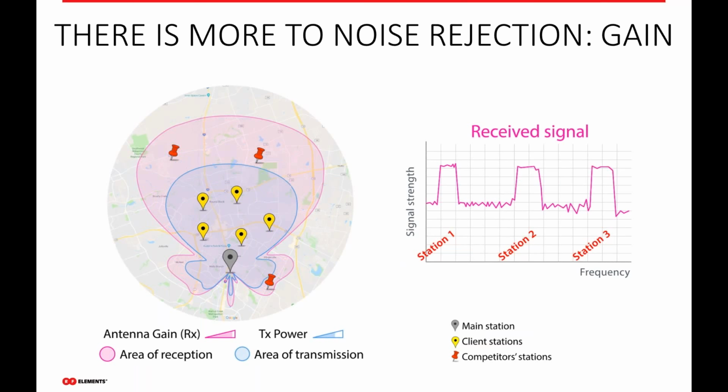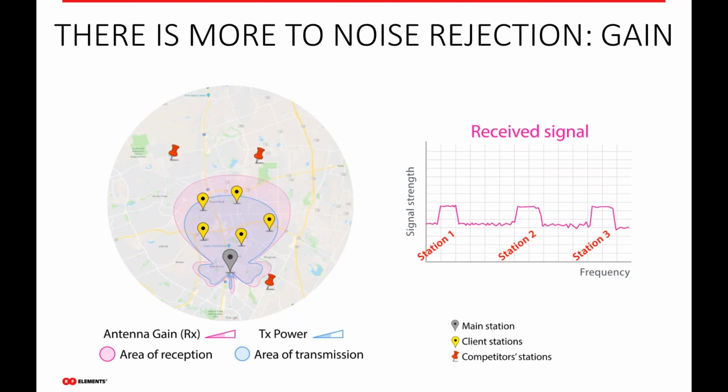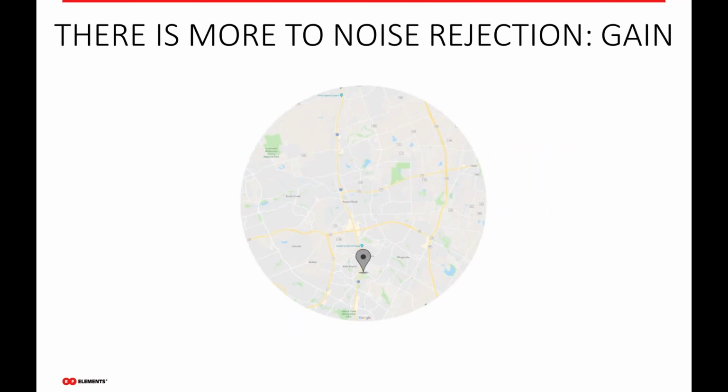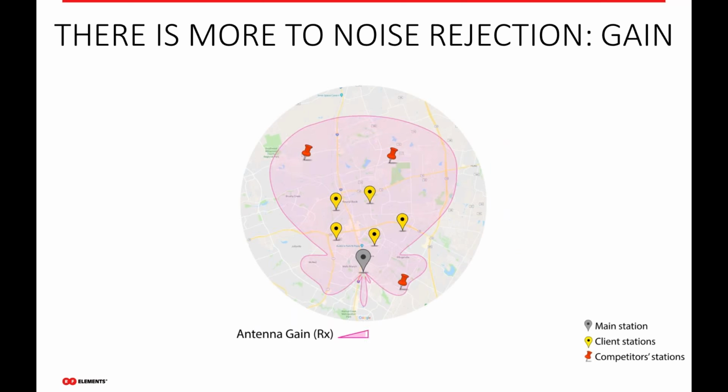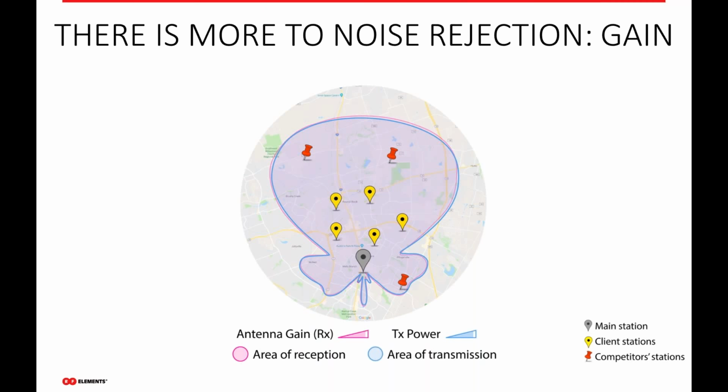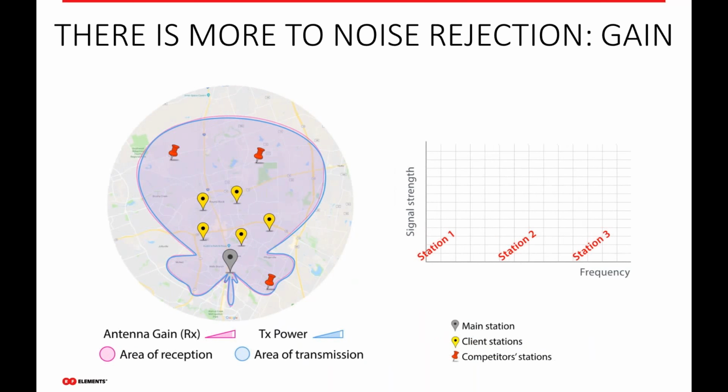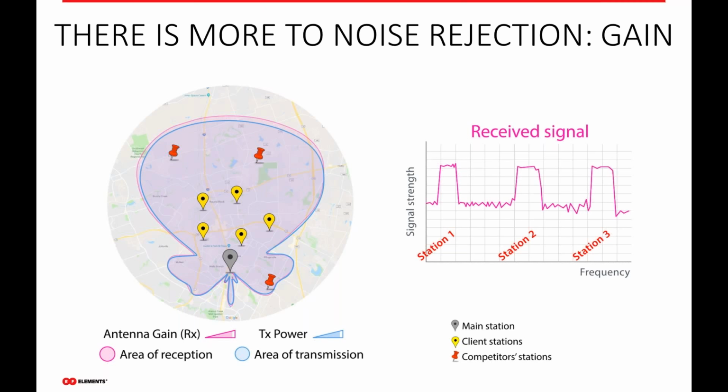If you use appropriate gain horns or even appropriate down tilt, you can see as we reduce the gain of the horn or the reception, we start now reducing the noise level of competing APs out at a distance, or again, even other noise sources that may be coming in. So it really doesn't make sense to use these really high gain patch array sector antennas for the new world of smaller and smaller cell coverage from our towers.